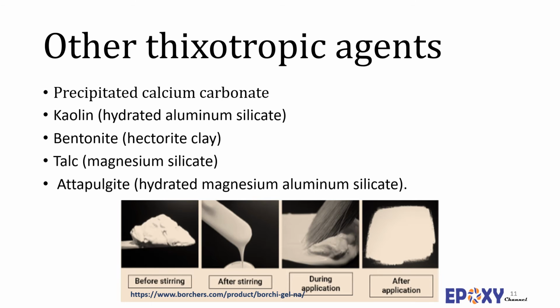Depending on the grade, kaolin can also control viscosity to prevent drip or sag, improve surface smoothness, provide reinforcement, and also reduce shrinkage. The finer particle sizes, for example, particle size of 0.5 micrometer or less, build viscosity more efficiently and provide better reinforcement than do their coarser counterparts.